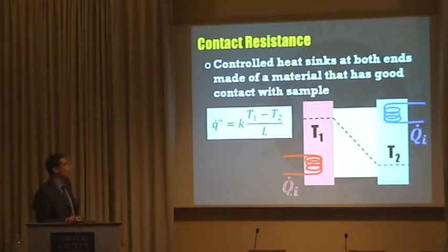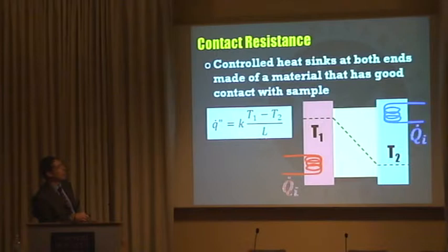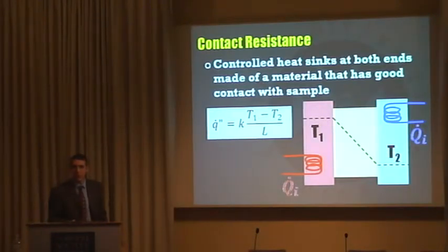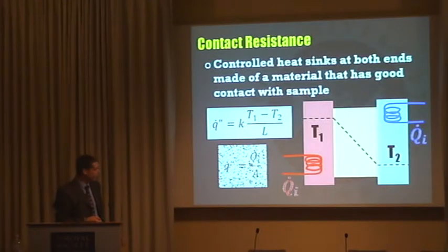Okay? So basically, my heat flux now is described by this simple equation, straight line, T1 minus T2 divided by L, which is the thickness, and then I have basically the heat flux to the problem. I have solved my problem. Okay? So by doing an experiment with the material, whatever I have in the middle, I can actually guarantee that now I have K, and with that K, I can actually solve the problem.